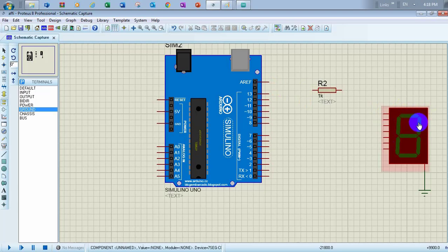So what do we do? We play with injecting or not injecting power by what? By this Arduino. So we link by resistors: one side of the resistor is linked with this 7 segment display, and the other side will link with an Arduino pin. For that we do this.